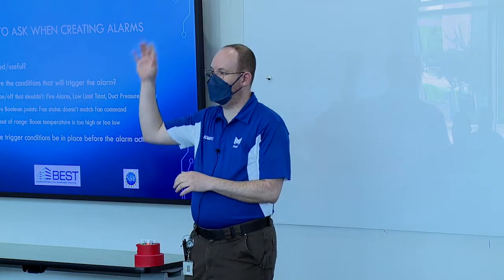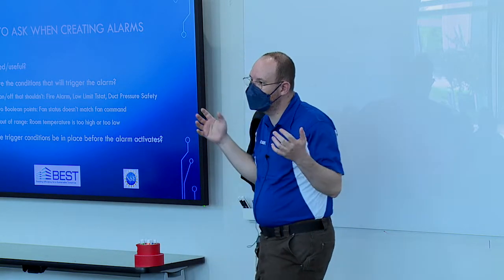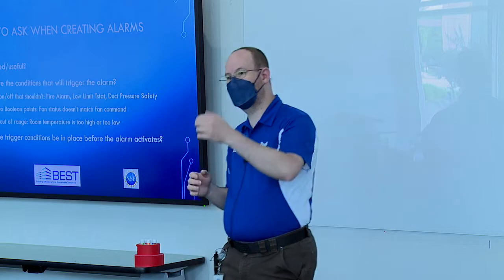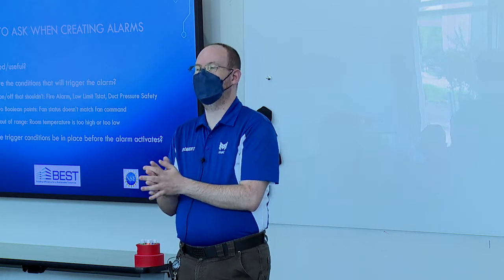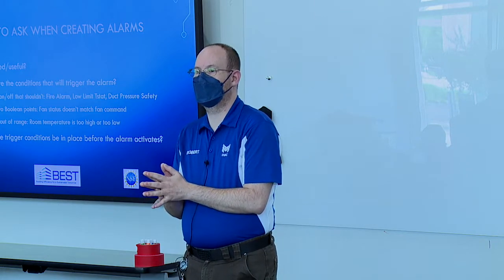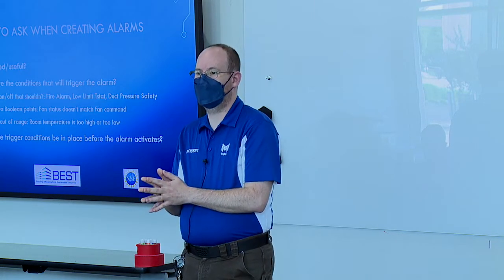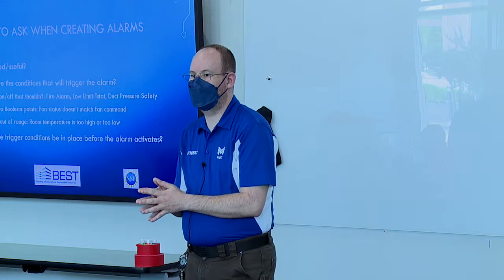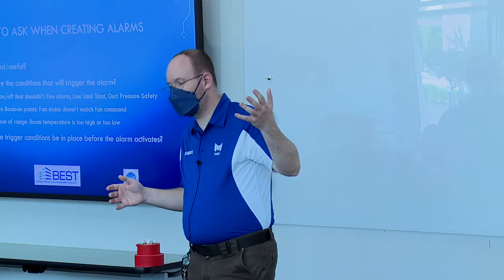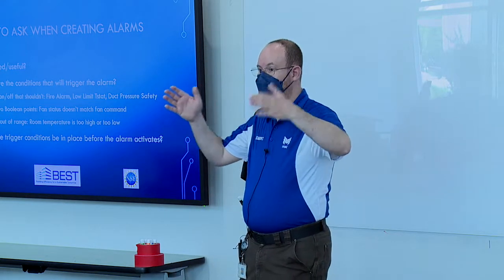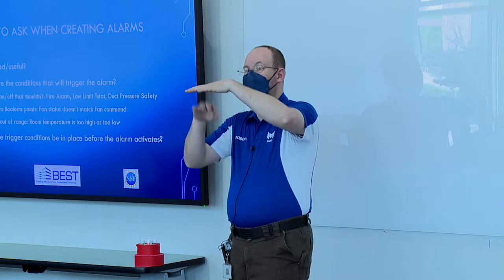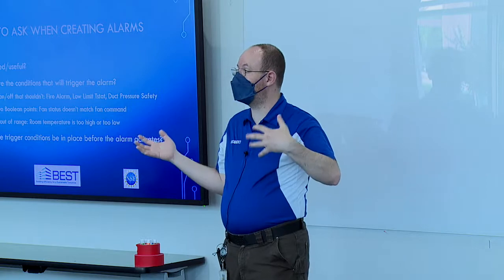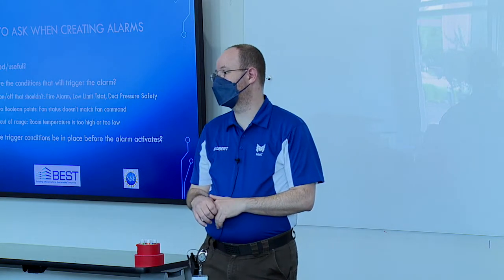I would kind of argue that maybe we need to set an alarm for that, to come slap whoever changed the set point that high. But also, what if you've got a range between 70 and 75, and you've got that alarm set at 72? You're still within that range, whether the unit may be off or not. Absolutely right. If we're existing within a deadband range, we better not have an alarm that exists in that same range. We need to take those kind of things into account.